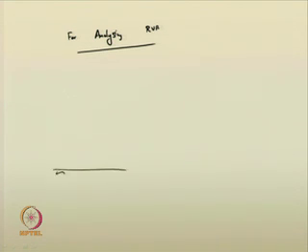Now, for analyzing rapidly varied flow, we suggested that the curvature is pronounced in rapidly varied flow. For example, in the hydraulic jump, within a short reach the elevation of water rises.